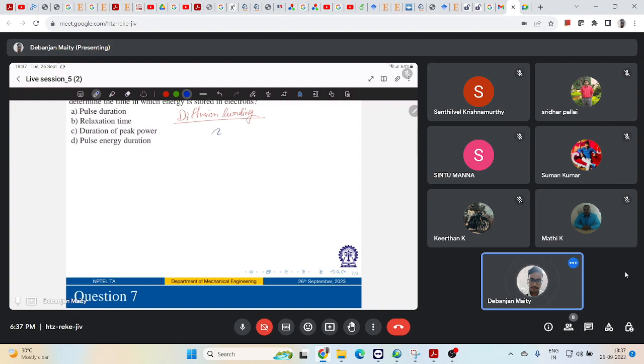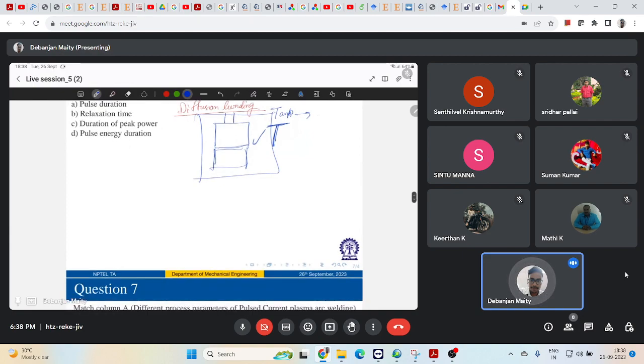And you put those two metal surfaces, the two kinds of metals, in a vacuum furnace and heat it to an isothermal temperature T from ambient temperature, and you can also apply pressure with a plunger, right?